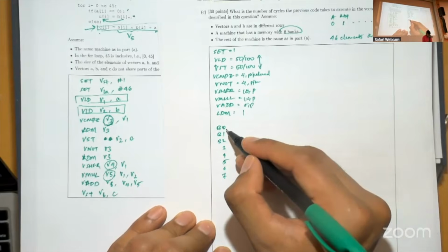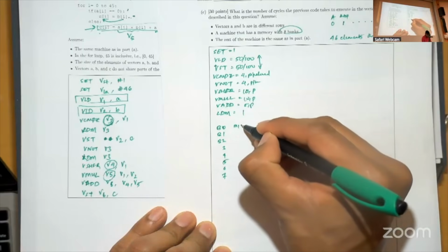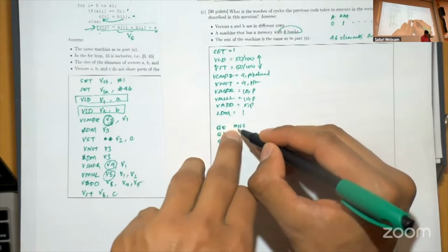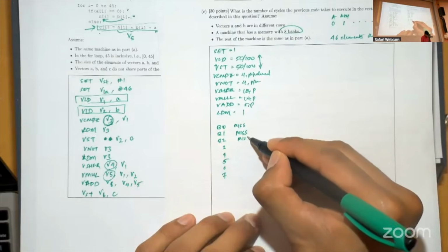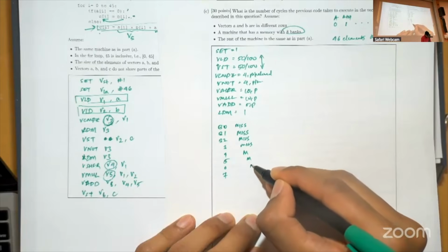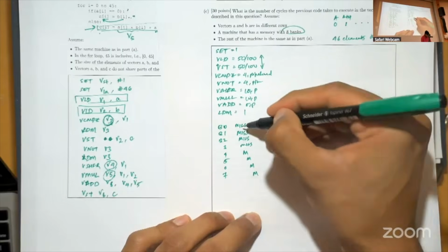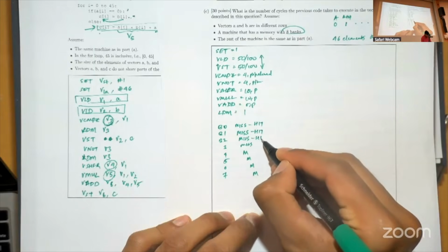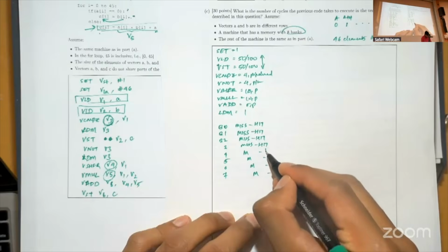Okay. The first access is always going to be a miss because everything is pre-charged. So you have a miss. And then after one cycle, you can issue another request to B1. That's also going to be a miss. You keep following this with misses, and I'm going to shorten this and write this as M. After the miss in the first one, you'd have a hit because the row is already open, right? And this follows here as well.